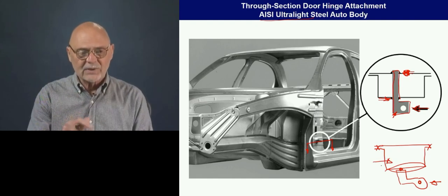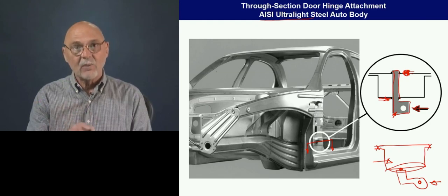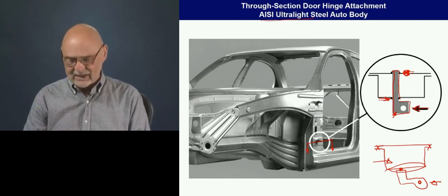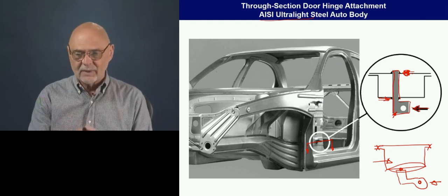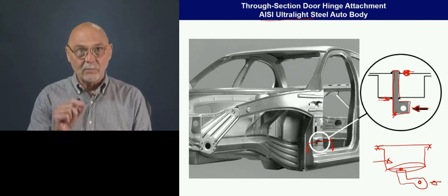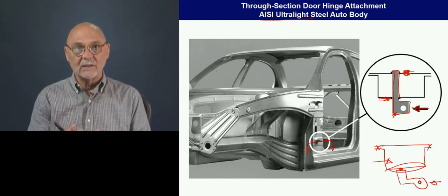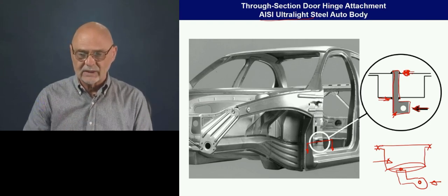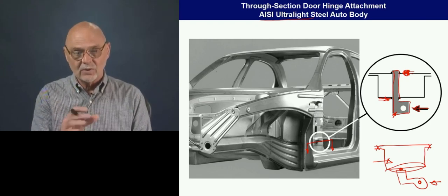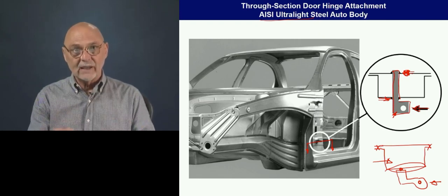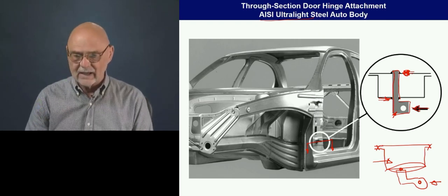Okay, so really what we just covered today is the idea of spot welding and some of the bad effects that it causes a structure. And we talked about this idea that whenever we have a point load coming into a thin wall beam, we really have to add a lot of reinforcement and very careful geometry in order to make sure that we get the true advantage of the big beam section as we load it.